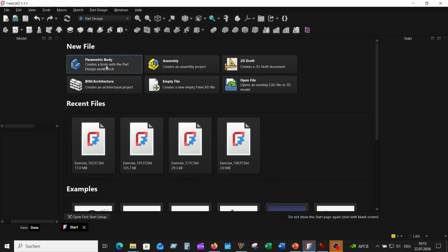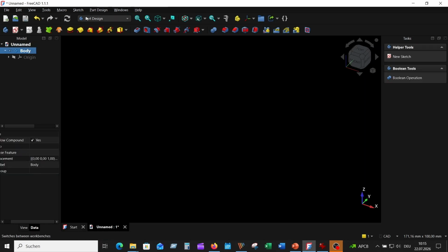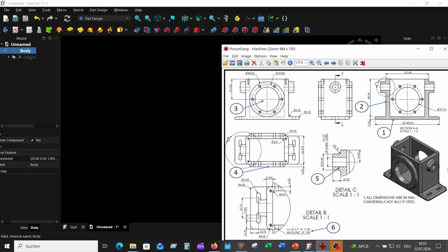First, click simply this button to start the FreeCAD workspace and to create the parametric solid part. In step 1, we sketch the position 1 profile with the slots on XY plane and create a solid part with the Extrude tool.